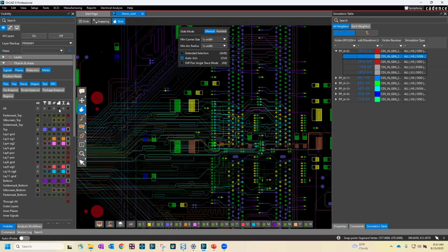If an impedance controlled trace has a target impedance of 100, but the impedance of this trace is 90 ohms on the inner layer, is it acceptable? Will it cause reflections? Yeah, I guess that's more of a question that you can model with this if you have the traces set up with those impedances on these different layers, but I think that's more of a question of your judgment, right? Yeah, exactly. It may or may not, depending on the signal that's going down there.